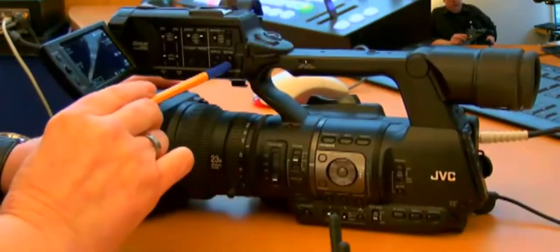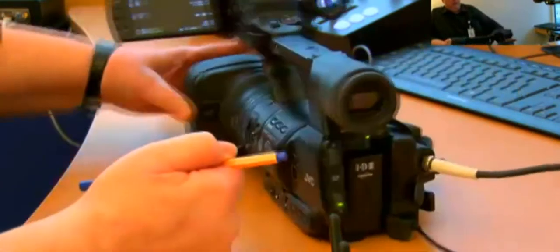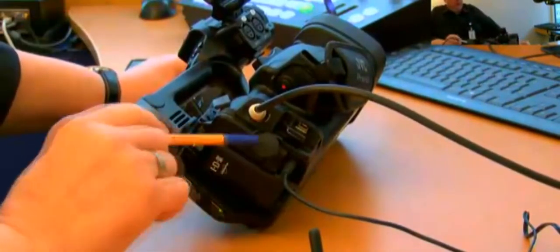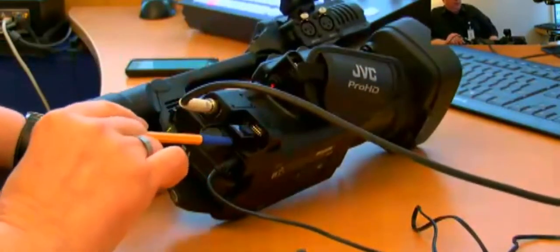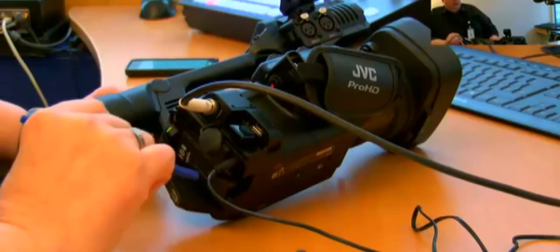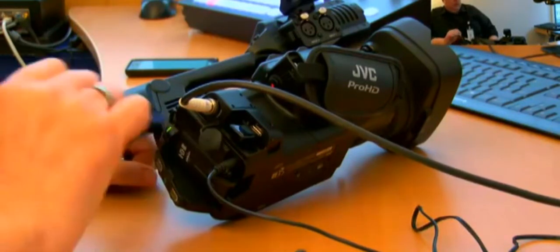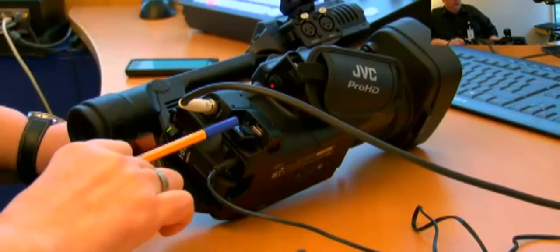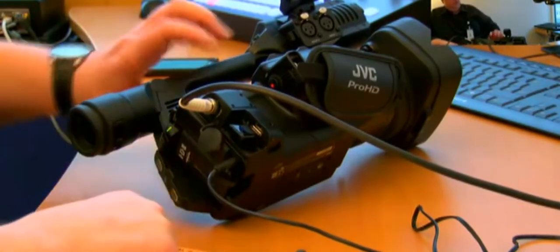Also, we're going to use the status button just to catch the information which we need. And we do a connection. Of course, keep in mind the 650 has the IP capability that makes it possible to do the live streaming. I use the USB host here, and I use a wireless connection here. It has a very small, tiny Wi-Fi dongle which I connect. But keep in mind, you can use a 3G dongle or a 4G dongle, or you can use a Cat5 USB converter here. So it doesn't care which kind of system you use. For our example today, this works as an access point, so we make a point-to-point connection to the Teratek decoder.